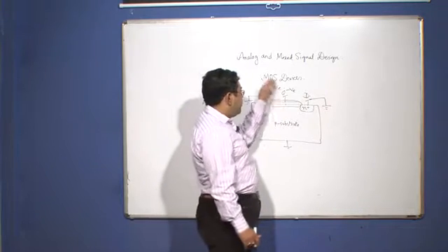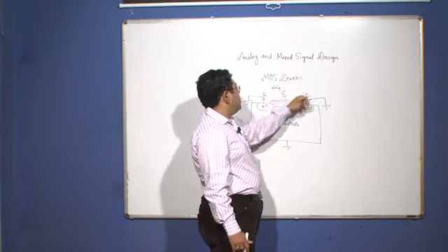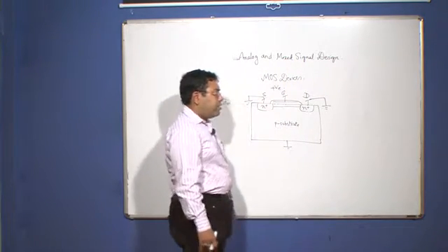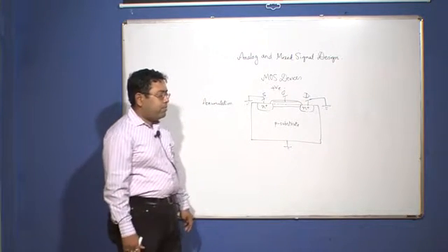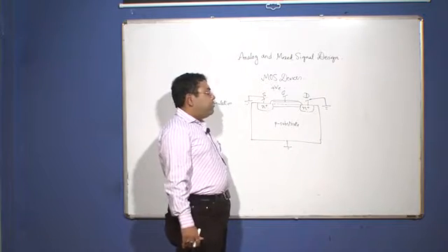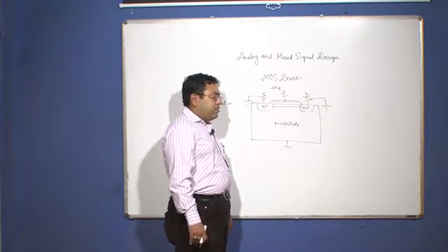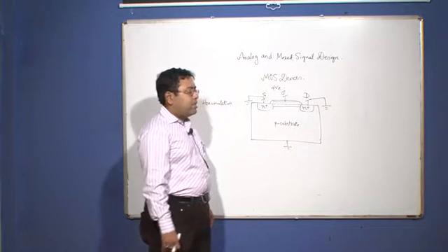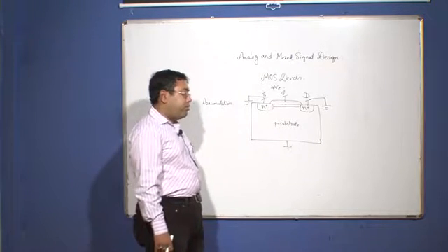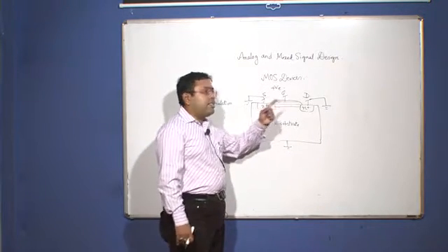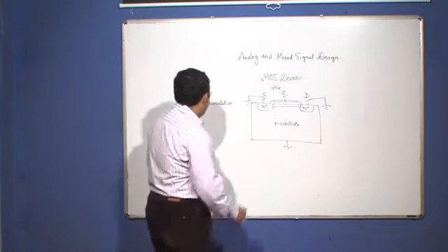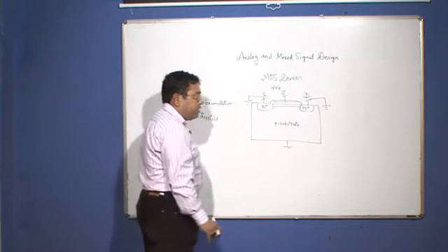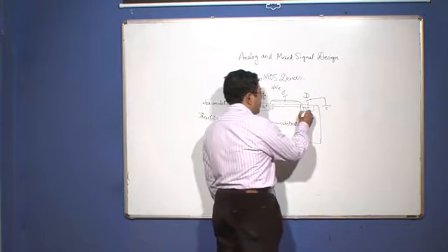Now, as you go on increasing the positive potential, the thickness of the depletion region becomes more and more, and you will find lesser and lesser holes in the depletion region, and at a particular potential, the density of charge carriers in the depletion region becomes so less that the concentration of electrons supersedes the concentration of holes, and we say that this layer gets inverted at that potential. So, this potential is known as the threshold voltage, and the phenomenon is known as inversion, or more popularly strong inversion.